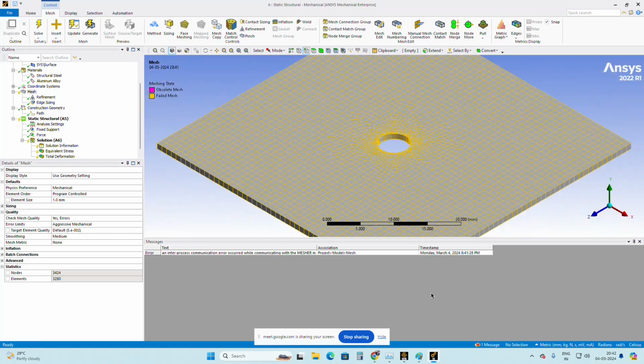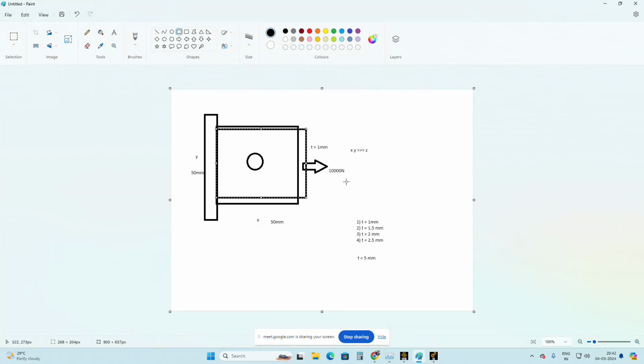So what we normally do, if you want a perfect mesh for this plate with hole, as I already told you, is convert this parametrical surface into a biparametrical one. In order to do that, we have to split the structure in this way, before meshing.